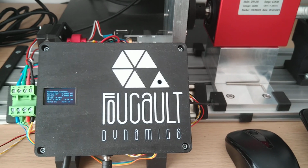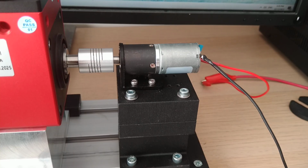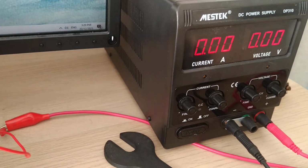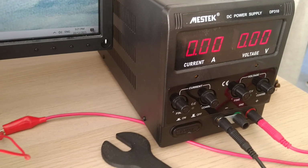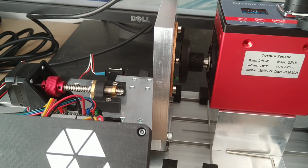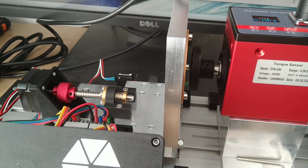communication protocol. So here on the right I have a simple dummy motor under test. It is a brushed DC motor with an inline planetary speed reducer, and here on the right I have a laboratory regulated DC power supply. So I'm going to start running the motor, and we will be observing how the Mini-Dyno's variable air gap permanent magnet eddy current resistance unit responds to the motor's operation.